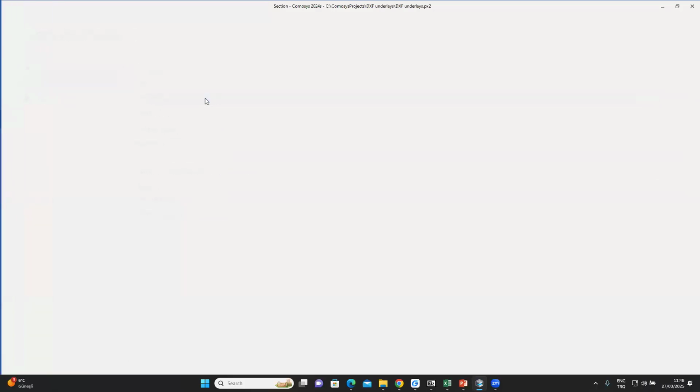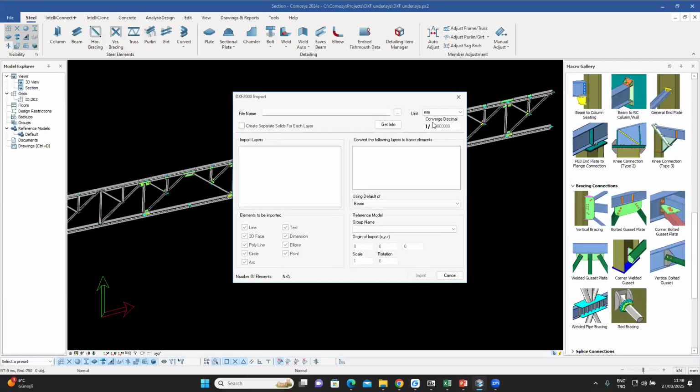before we continue to the drawing side, and that is that DXF files, like I mentioned, can be problematic. Sometimes, for example, a distance of 10,000 could be written as 9,999.96, or some small mistakes here and there. And so while you're importing, you can give a decimal precision. So it will round off.